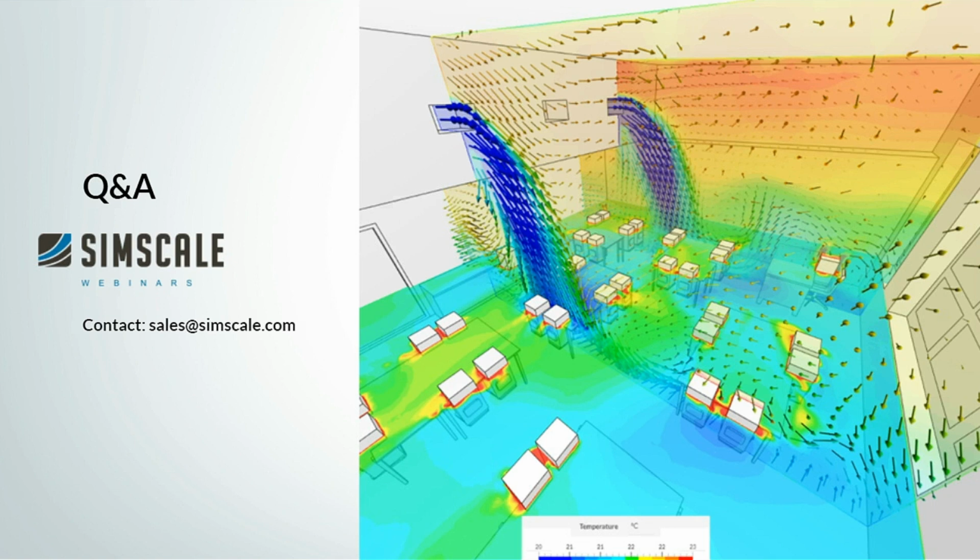Then there's a question regarding the geometry from other software, if we have to introduce the wall thickness. So we have different modules in SimScale. What we've seen here today was the convective heat transfer analysis, where we start with the fluid volume only. We have a conjugate heat transfer analysis as well, where you can bring in the fluid and also the walls